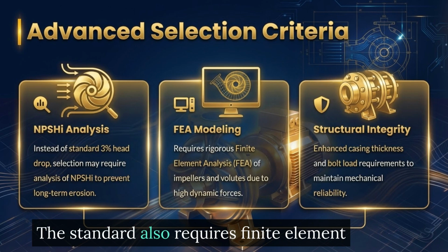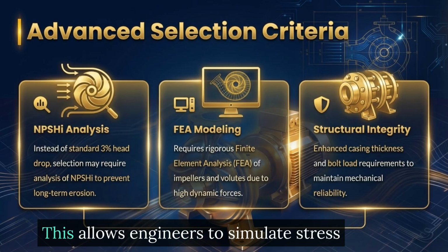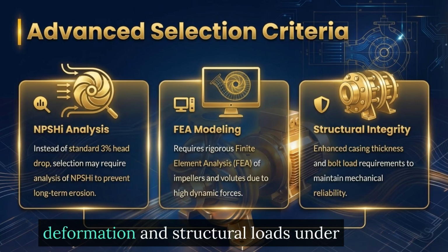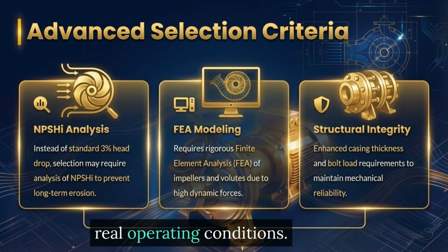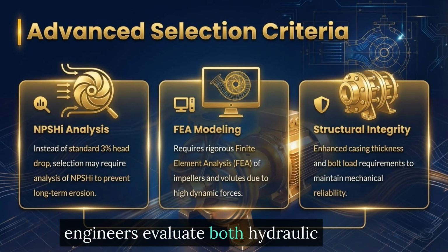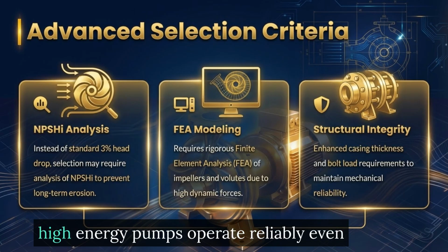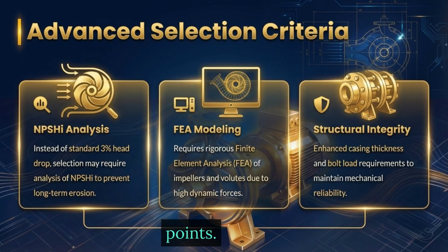The standard also requires finite element analysis, or FEA, for critical components like impellers. This allows engineers to simulate stress, deformation, and structural loads under real operating conditions. So, in essence, the new criteria push engineers to evaluate both hydraulic behavior and structural strength, ensuring high energy pumps operate reliably even under extreme conditions.